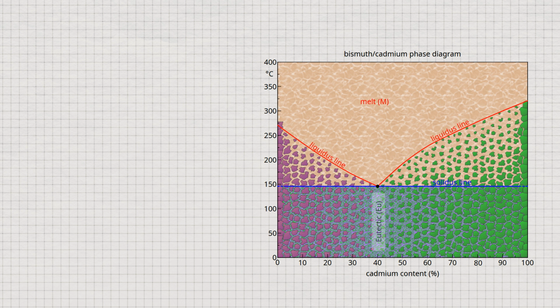In eutectic alloys, the microstructure consists entirely of the eutectic, a very fine mixture of pure crystals of the respective components. In hypoeutectic alloys, the primary precipitated crystals of the base material are also present in the microstructure. In hypereutectic alloys, the primary precipitated crystals of the alloying component occur in addition to the eutectic.